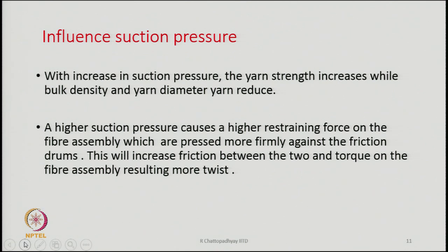Next, another important parameter is suction pressure. The whole purpose of suction is to make sure that the fibers which are at the nip of the two friction drums remain pressed against the friction drum.